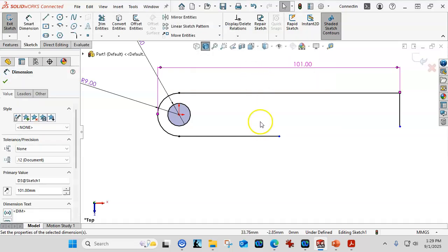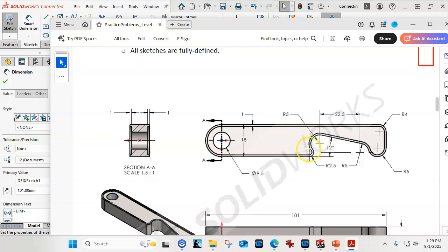Okay, so this will be a sketch fillet, and I'm not going to worry about the sketch fillets until I'm done because I think this is going to become just tangent arc to line to tangent arc, and then wherever that becomes tangent, tangent.